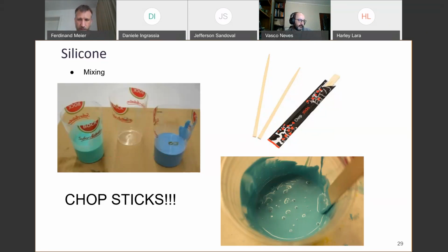Yes, you're going to waste a few euros on material, but this is very helpful for making sure that you don't have any reaction with your mixing chopsticks, that it doesn't stick to your material or to your mold. So in the end, you kind of save money by making a first coupon, as Neil calls them, and I think I'm reaching the end.